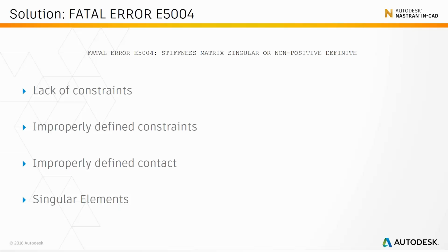So realistically, the two areas that you would primarily go back to are: have I defined my constraints, and how have I defined my contacts, and are they sufficient to constrain the part?